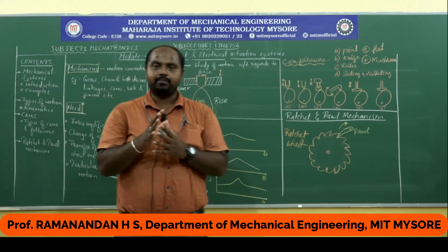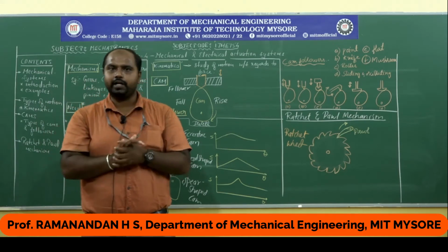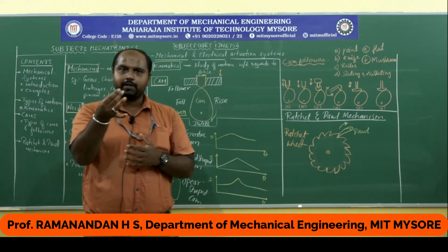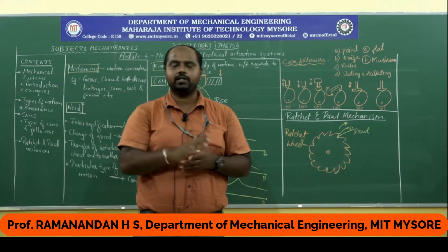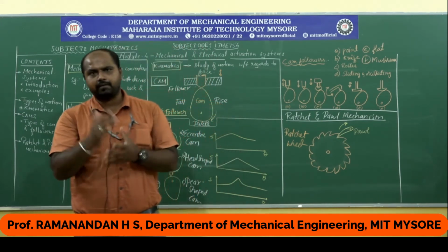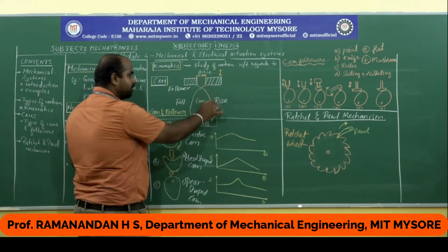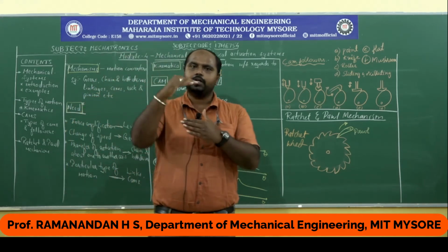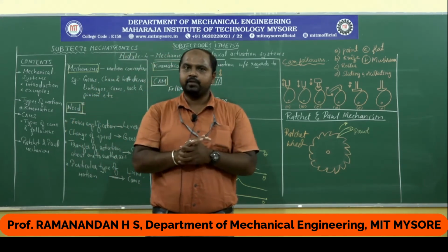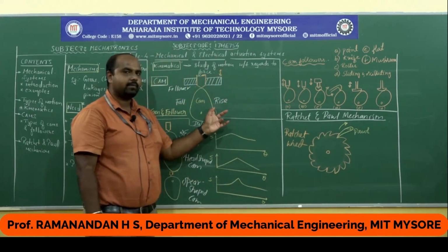Okay, in the engine, the valve should be open for the petrol and air mixture to enter. So, what should be the period of time so that your petrol air mixture enters into your petrol engine? Fix the period of time. That time will be defined by your cam profile, because the valve does not understand the amount of time it should keep the inlet valve open. That I will be defining with the help of the cam profile, the cam and the follower.